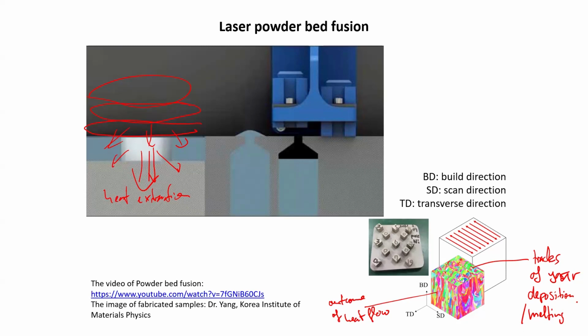So you introduce a lot of strain because of shrinkage going through the liquid to solid transformation and due to the cooling. And that means you create strain, which can also introduce huge dislocation density. So the strain is actually large enough to go above the elastic limit into the plastic regime. And this is a highly defected structure which you get.